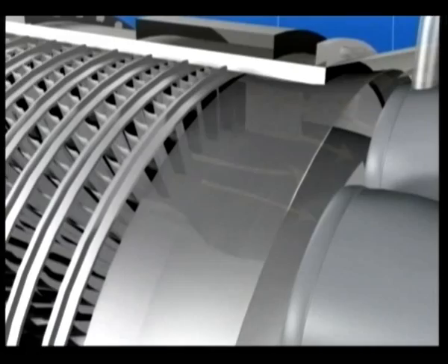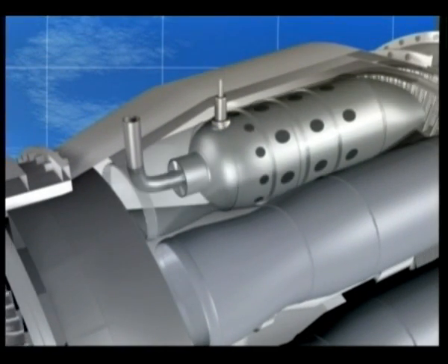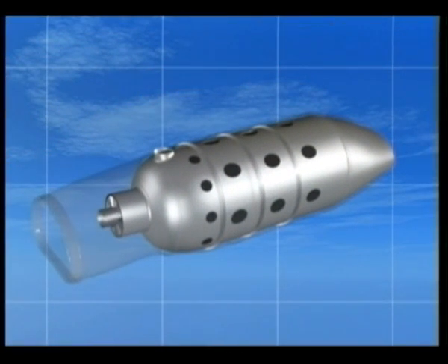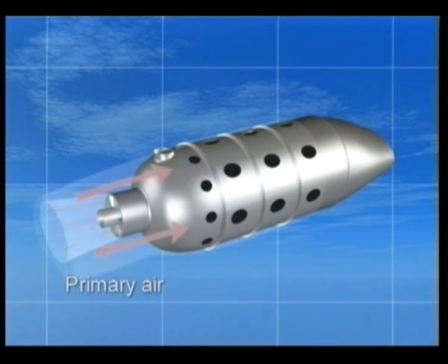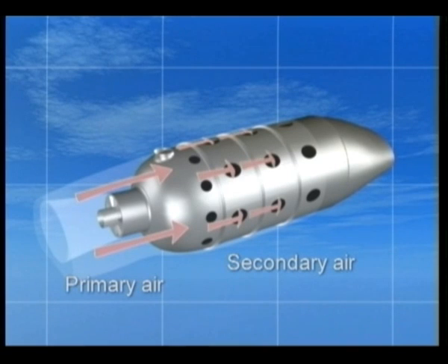On leaving the diffuser, the air passes into the combustion chambers. Of the total mass of air passing to the combustion chambers, approximately 25%, known as primary air, enters the flame tubes through the flame tube orifice and is used for combustion. The remainder of the air passes along the outside of the flame tubes, entering through dilution holes in the side of the tubes, and is used for cooling.